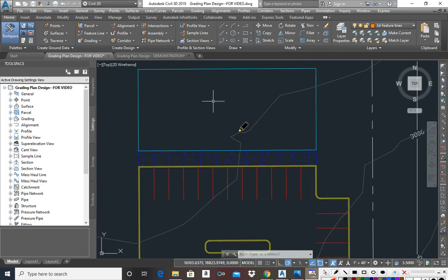The 2% slope on the sidewalk is for the sidewalk in front, and the 2% will be across in this direction. This is where we're going to have the 2%, and that's very typical of sidewalks. So remember, the building is going to be flat, the 2% sidewalk cross slope will be here, and then water will be flowing in this direction. So remember, this is where we need to have the minimum of 0.5% and maximum of 5% grades.